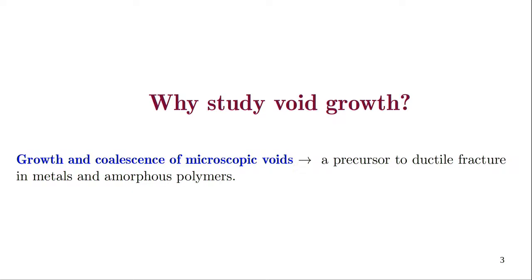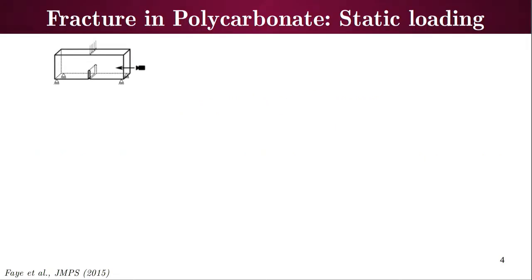Before we go into the simulations of void growth, I would like to show some experiments which I did way back during my PhD. This is a 3-point bend specimen, which is generally used for doing the fracture test. It has a pre-existing crack, it is supported at two ends, and then we apply load at the top so that the crack opens in mode 1 loading. Okay.